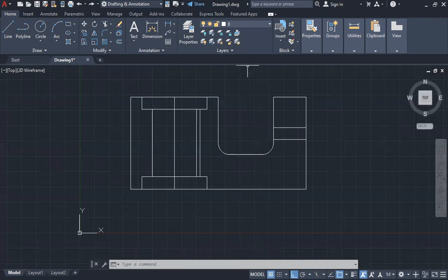Okay, don't forget there's a line that goes from this point right to your center line. If you look on your drawing, you've got this line that goes right to the center. You could draw a line from that point and join it across, or you could just extend your line. So if you click on a line, you have 3 reference points on that line. You have the 2 ends and then the middle of that line.